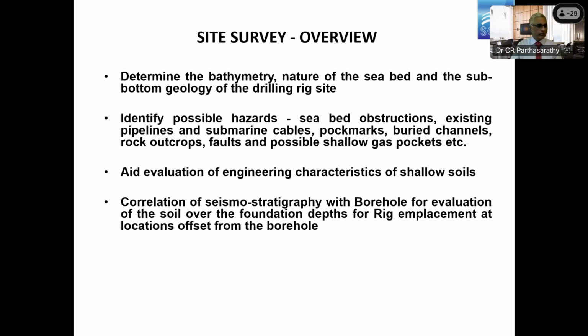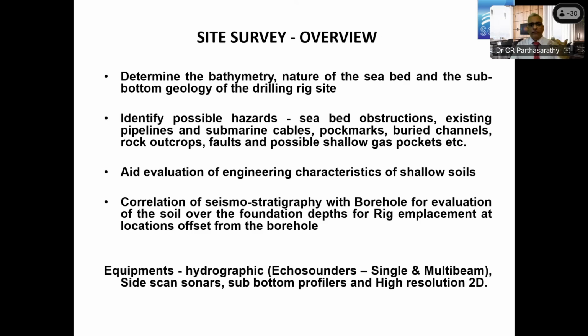There are certain locations where they take the geophysical and geotechnical borehole data and put that into the form of a geological model, and that geological model is used to evaluate the characteristics of the ground for any subsequent moving of the rig to the locations.